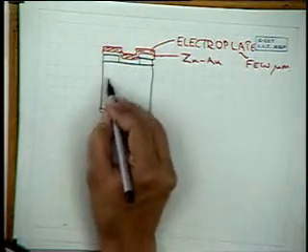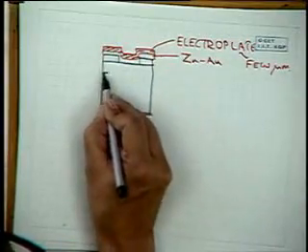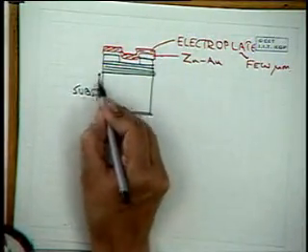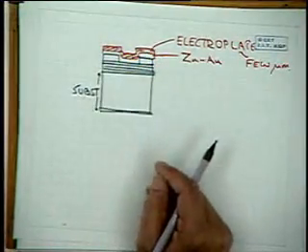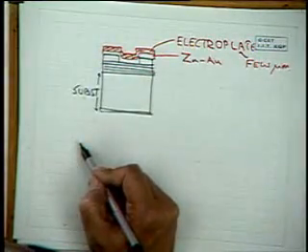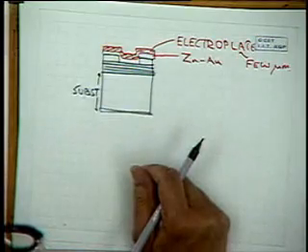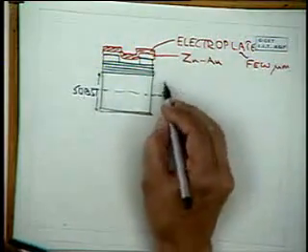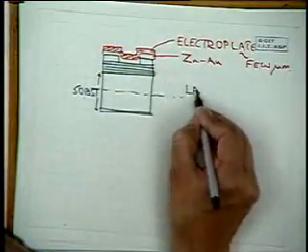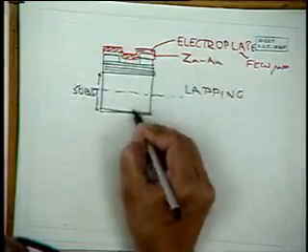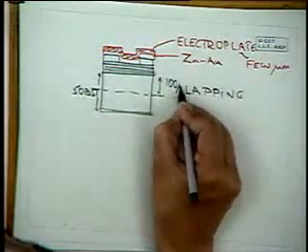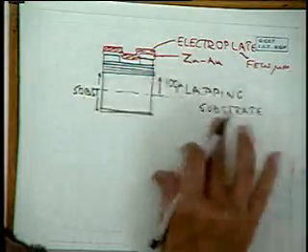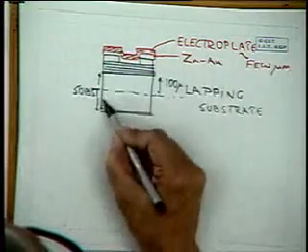Now we started off with, if we draw it to the right geometry, the layers are over here, and this is the substrate, which is 350 microns. To form the cavity, we have to cleave. Cleavage is done much more easily and more uniformly if we can thin the substrate. So by lapping, this is an important step. We lap the substrate down to about 100 microns. This can be done over the whole wafer, the whole piece. So this is removed.